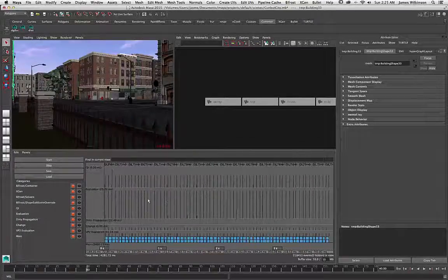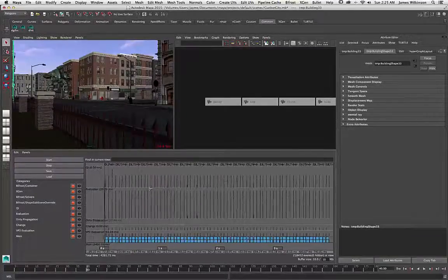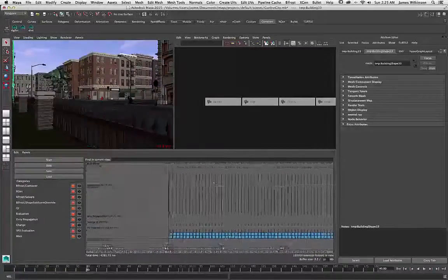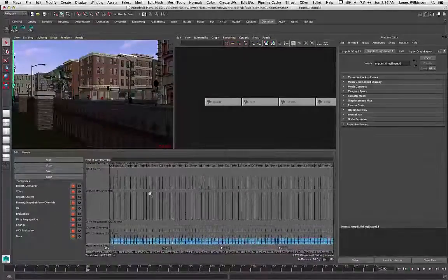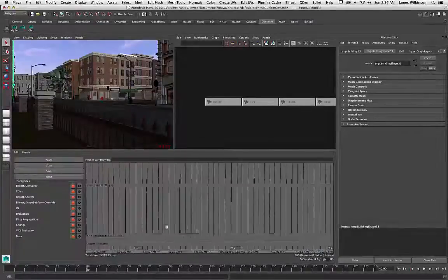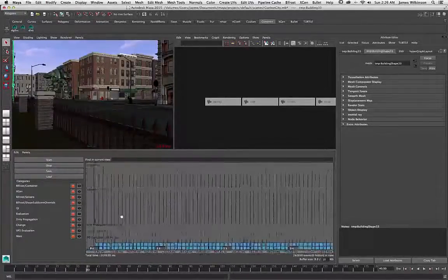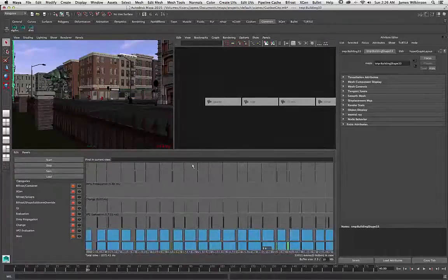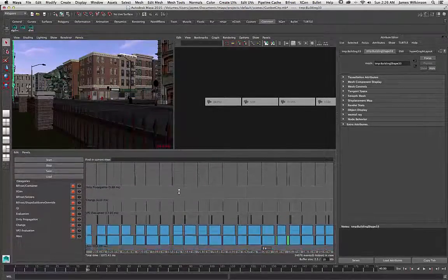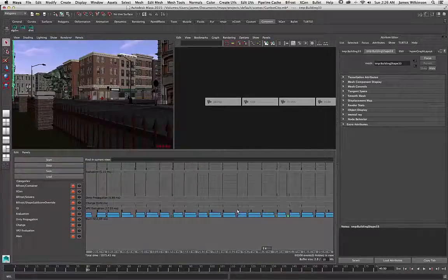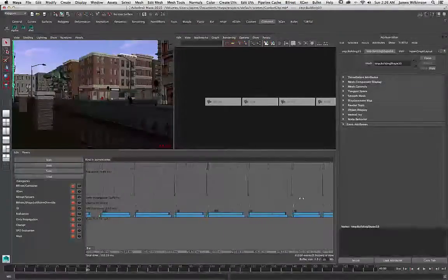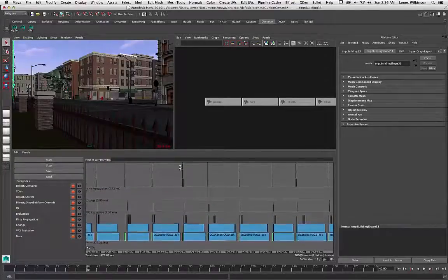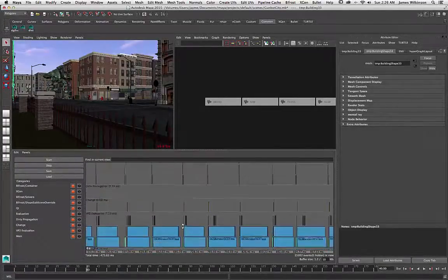Using the standard pan button, the Alt and left mouse button, the middle mouse button, you can actually go through and pan the view around. You can also zoom into it. You'll also notice that the zoom maintains the aspect ratio. So in a lot of cases you want to be able to squish it down. If you hold the shift key and right click, you can scale it in the vertical direction or in the horizontal direction, so you can expand out the view or compress or stretch out the view.